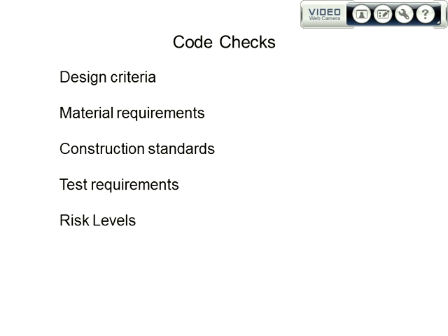Okay. So, to be honest, when you're comparing construction standards, there are a number of issues, but the main ones you could think of: what does the code say the pipeline's got to be buried at? What depth? What does it say about the inspection of the pipeline during construction? In other words, do you have to fully inspect all field welds or not?